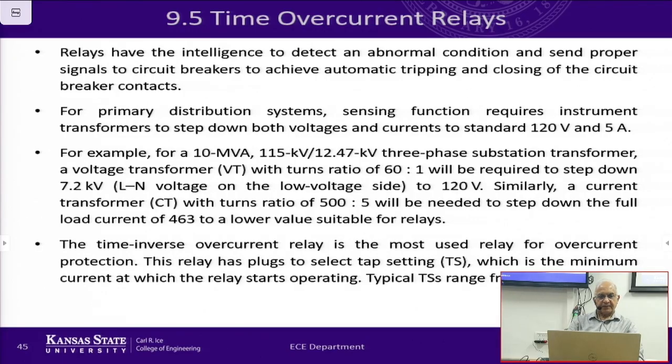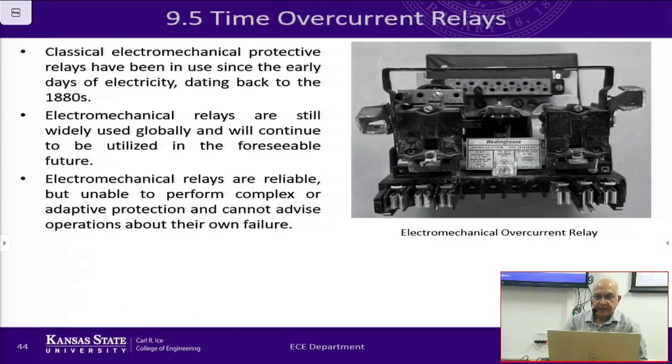Now, the time inverse over current relay is the most commonly used relay, and it has tap settings. If you look at the picture here, right there at the top, you see some plugs. These are the plugs where there are holes, and you see that there is a plug in one of them right here. That plug is the tap setting.